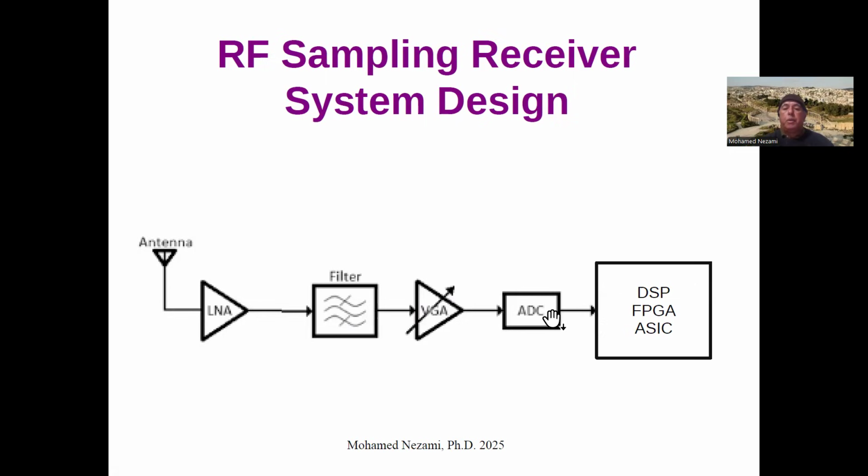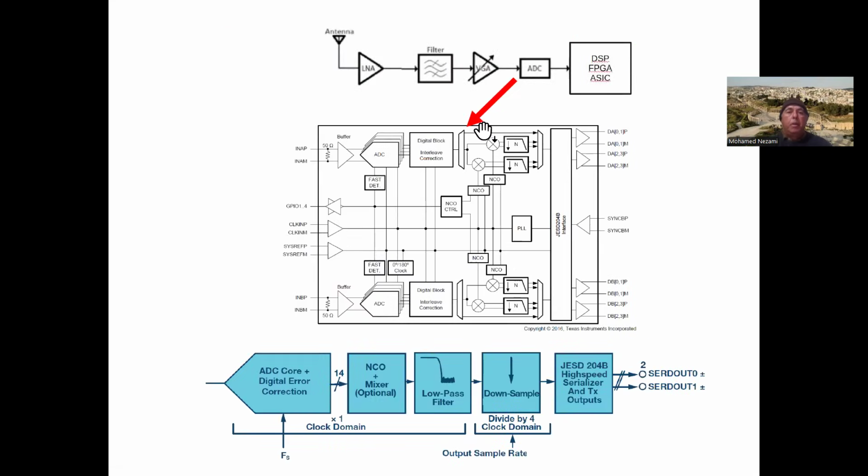So for these gigasamples per second, tremendously oversampling converters, the serial interface between the DSP platform and the A to D chip has been reduced further by including the decimation and frequency translation in the ADC, as we have shown previously with devices offered from Texas Instruments and Analog Devices and so on.